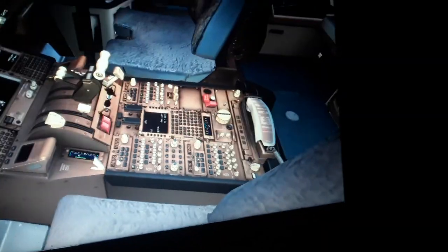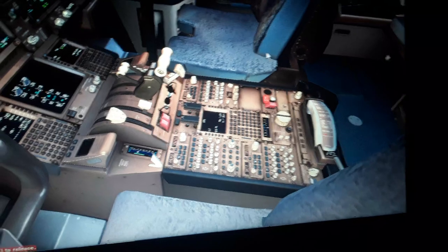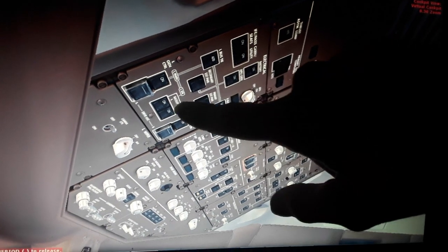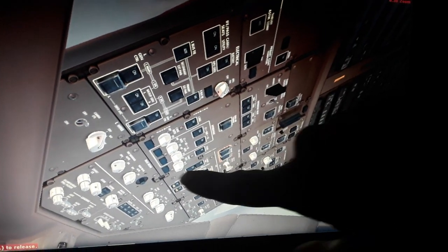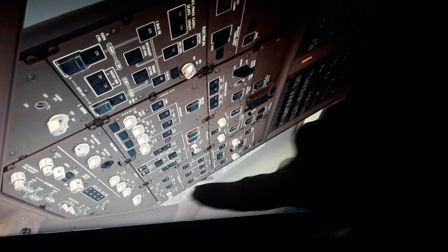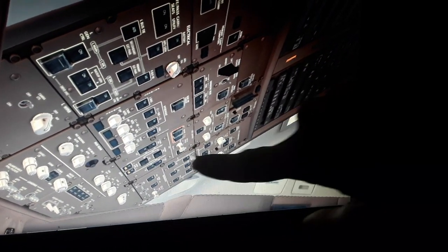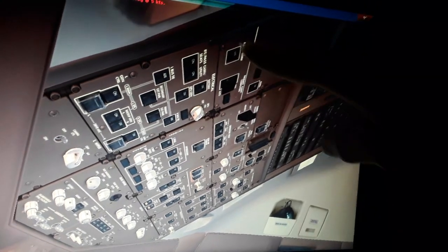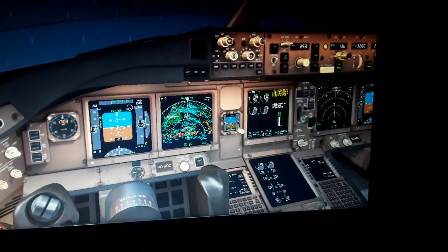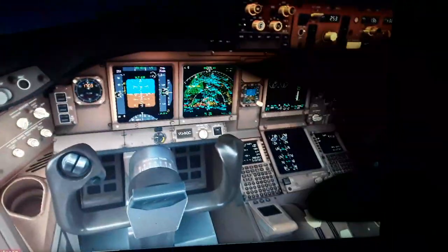So you also have other navigation communication panels, transmitter, receiver, the left and the right engine, the electrical, the hydraulic, the fuel pumps and tanks, electronic engine control for the engines, and the bleed, the pressurization from the engine and the APU, the primary flight control computers and the ADIRU, the air data inertial reference unit that controls and displays all the air data you see here.